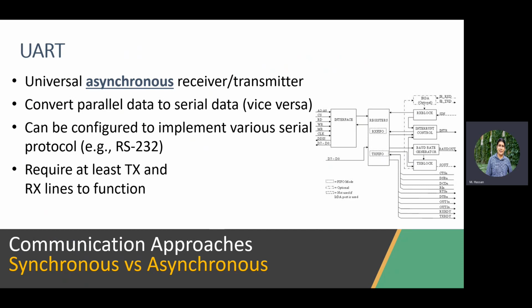And the important part is because you want to operate at a particular speed, you need buffers, right? This is very common also in asynchronous communication: you need buffers because the data arrives in a non-synchronized way. So the sender might be sending data while the receiver is not ready. So what would happen is you will buffer that data into either a TX or RX buffer, and then later on you will consume it.